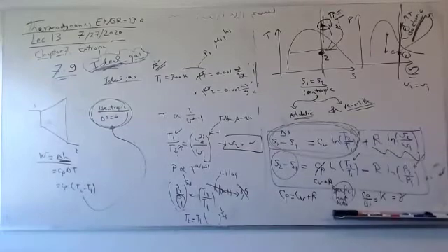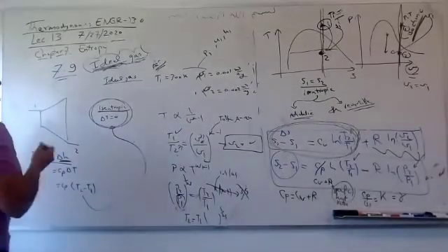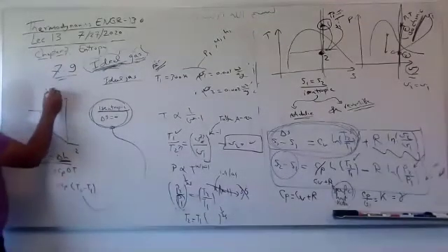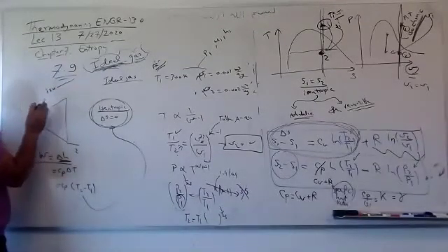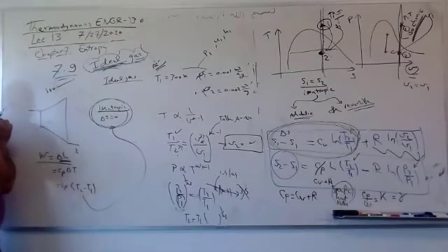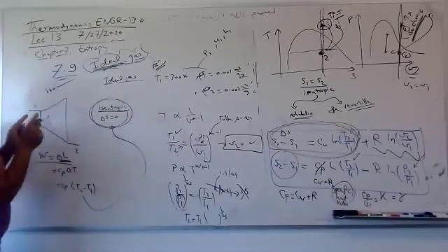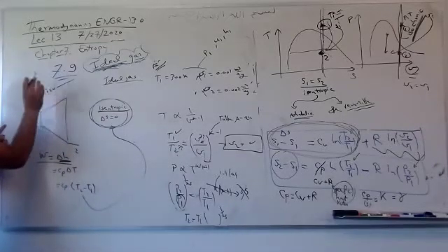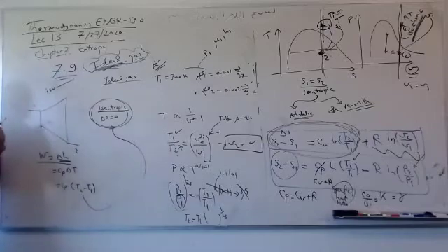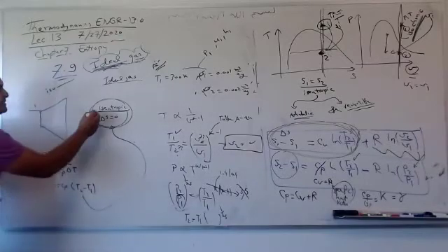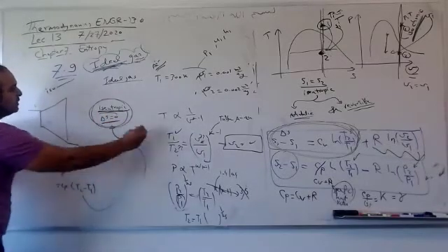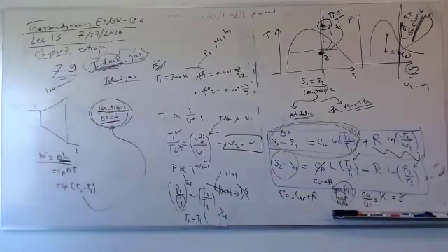So again, very simply, when I say isothermal, iso something, it means something is constant. So I don't need to give you the two temperatures. If I say isothermal, take T1, give it to T2. Isobaric, take P1, give it to P2. Isochoric, isometric, take V1 and give it to V2. Isentropic, take S1 to S2, or use this formulation for ideal gas.